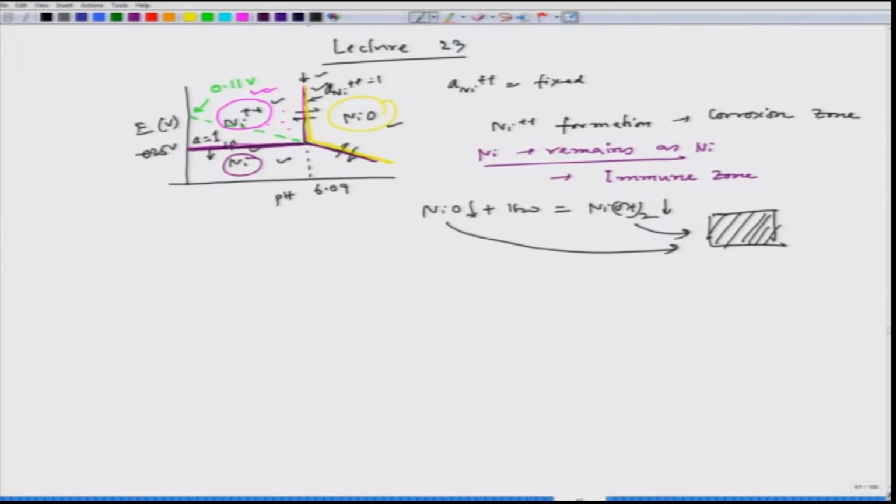Though nickel corrosion is taking place depending on the solubility of nickel plus plus ion and 2OH minus ion. So, depending on that, the solubility will decide how much nickel plus plus ion would exist in the solution, but that solubility would be so low. So, the nickel ion presence would be so low. That time we call it passivation.